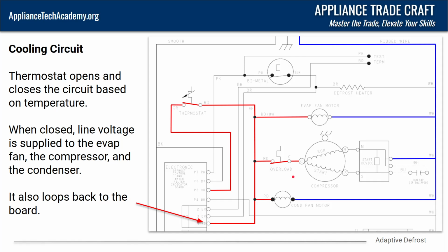So it's a diagnostic approach. If you're out on a service call and the compressor's not running, but your evaporator fan is and your condenser fan is, there's no need to check the board because we know we're getting the voltage and they should be working. With that being said, we're not really going into diagnostics too deep here.